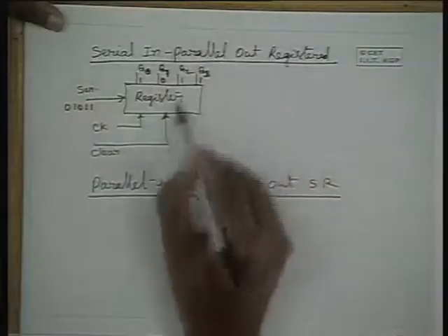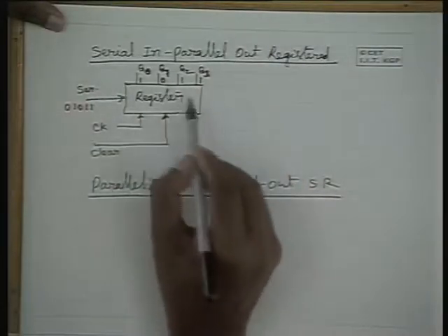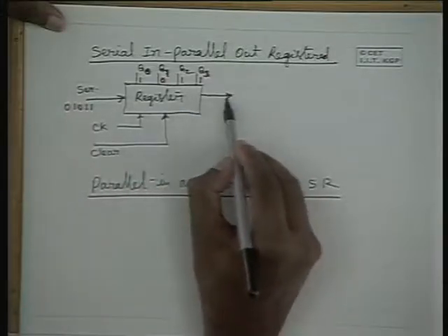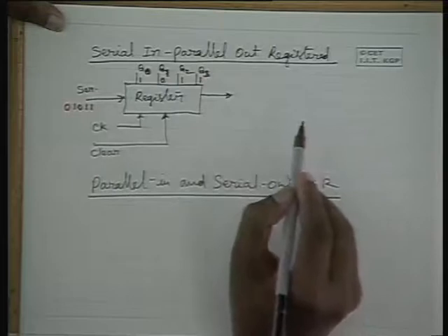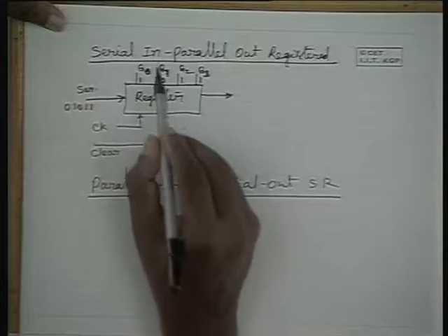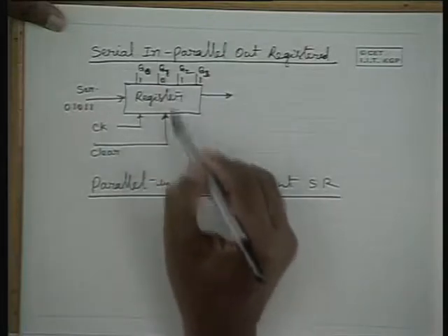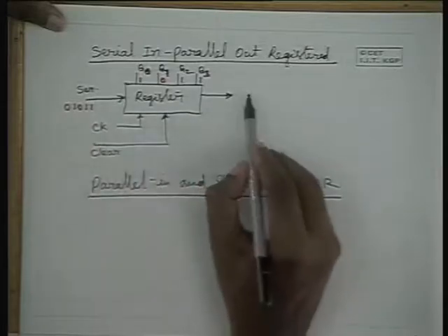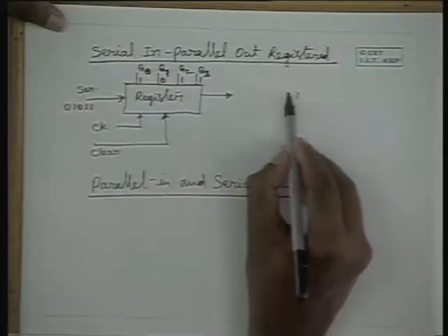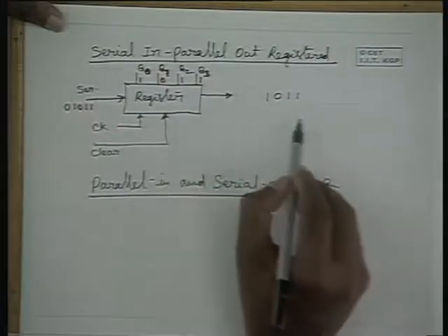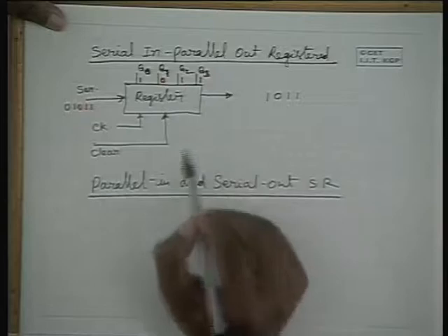So what it means is, we can store data into the shift register parallelly, and by means of clock pulse application we can get this data sequentially. Suppose 1101 is applied to the register parallelly, it is entered into the register, and then with clock pulses, if you want this output to be available sequentially, 1 bit after another in the same order, this can be used.